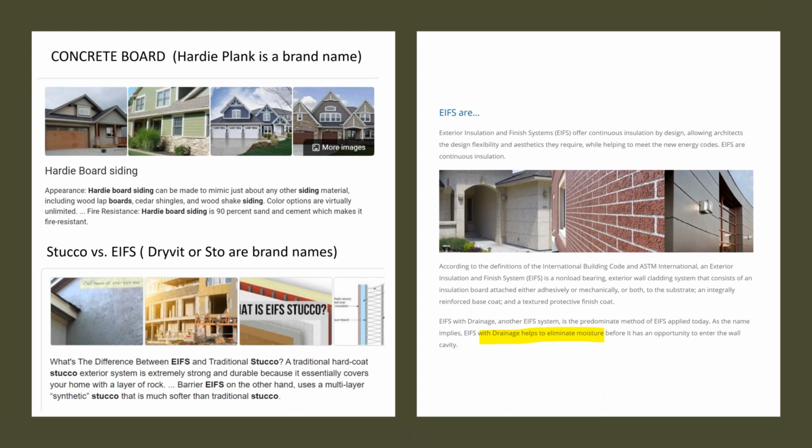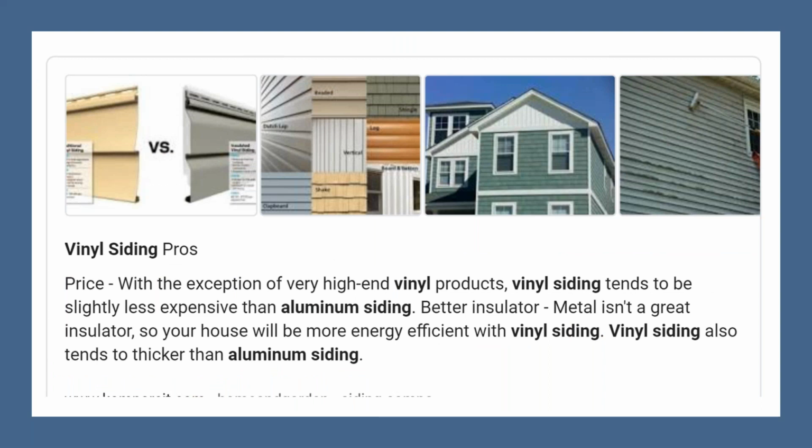If it was styrofoam, then it was definitely an EIFS wall. Yeah. There are different varieties of vinyl siding. You can buy vinyl that is insulated, and it's kind of a tough picture to see, but you can see there's insulation stuffed in between here, where on this one there is not. So this is obviously going to be more expensive, but don't judge a book by its cover. Just because it's a vinyl sided house doesn't necessarily mean it's an inferior product. So, because there are different kinds of vinyl.